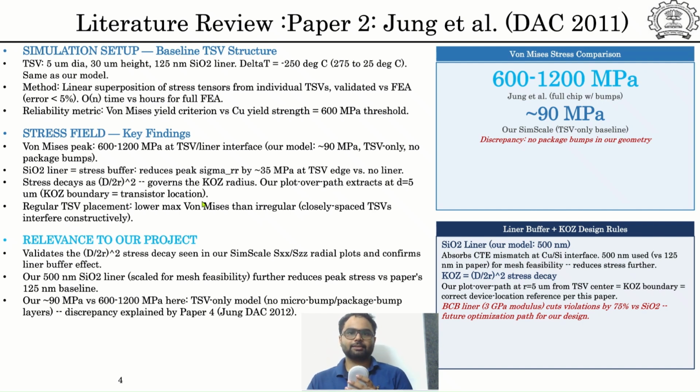Now I will discuss the second paper by Jung et al., which focuses on TSV stress-aware full chip reliability analysis. Coming to the simulation setup, they considered a TSV structure with copper and SiO2 liner and applied a temperature change from 275 to 25 degrees Celsius, which generates stress due to the CTE mismatch between copper and silicon. Instead of full chip FEA, they used linear superposition of the stress tensor, which is faster and accurate. They used the von Mises criterion, whose failure limit is around 600 megapascal.